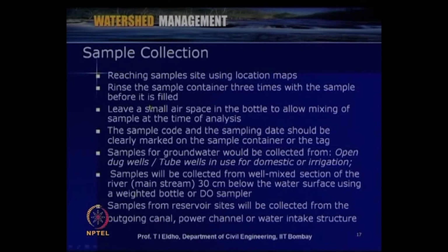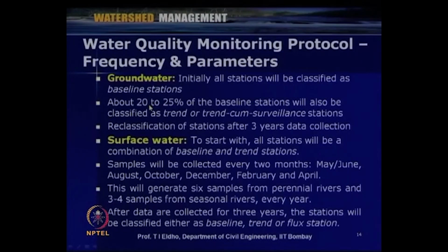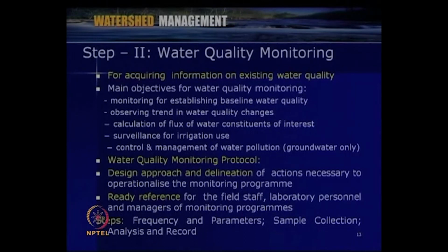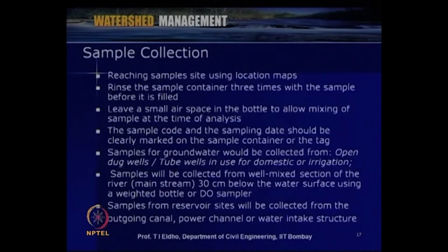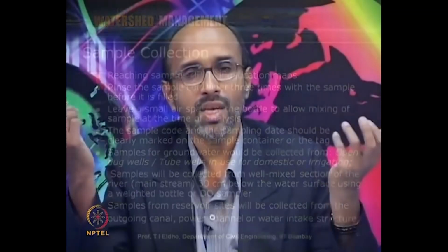So now, as far as this step, water quality monitoring, is concerned, another important issue is how to take the samples. Sample collection is one of the important issues, so we have to collect these samples appropriately, store them appropriately, and then send them to the laboratories for various testing purposes, so that we get the appropriate results through which we can make sure that the guidelines are met or not.